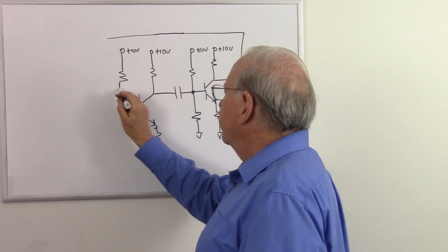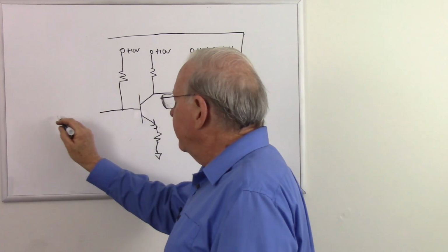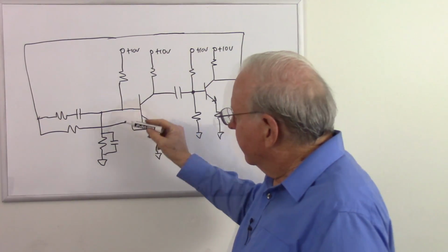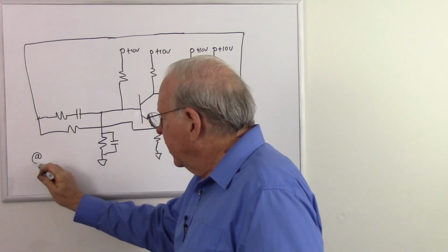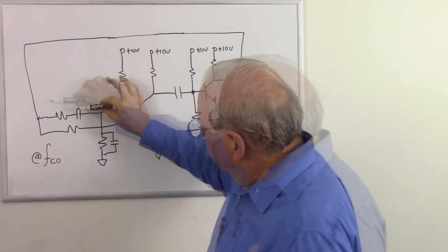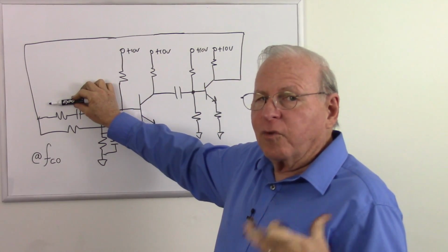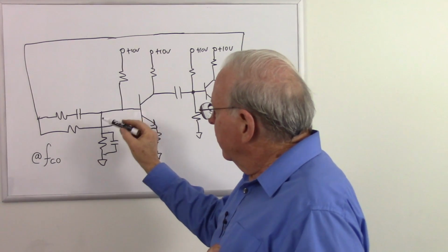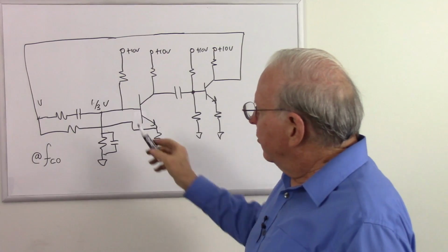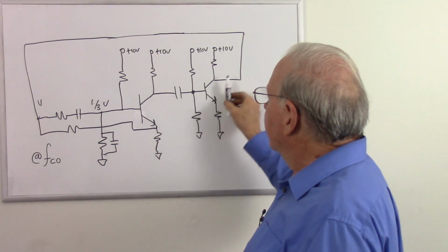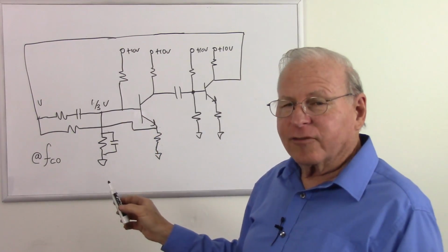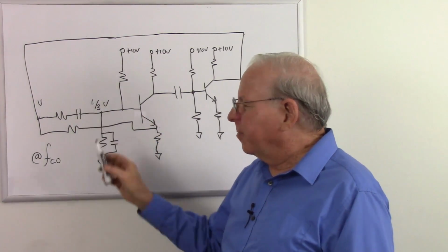So after all of that, let's go back to our Wien-bridge oscillator. So now we're back to our filters here. So what do we say? At our cutoff frequency, the frequency we want this to oscillate at, this will be acting basically like a resistor that's twice the value of this resistor. So whatever voltage we have here, we're going to have 1/3 of that voltage here, which means that to have a gain of 1, our amplifier has to have a total gain of 3 to match our 3-to-1 loss over here. So I said all of that just to explain that little bit there.